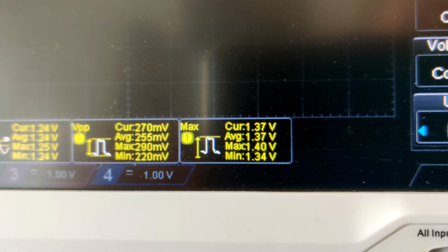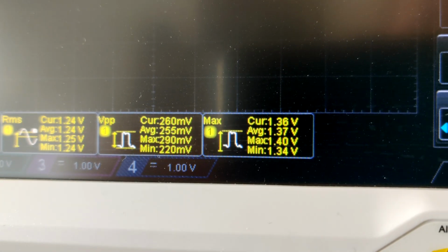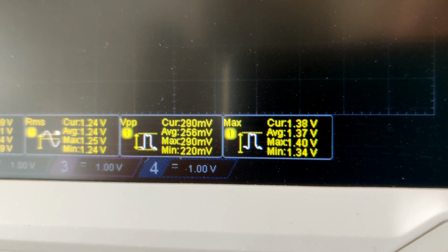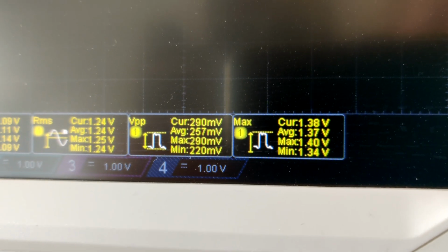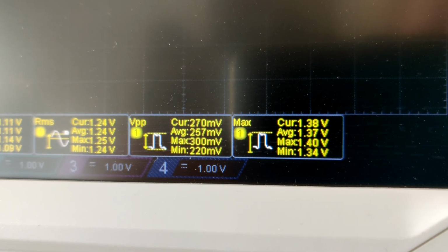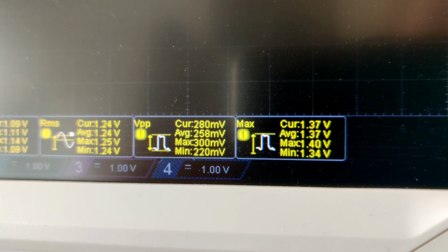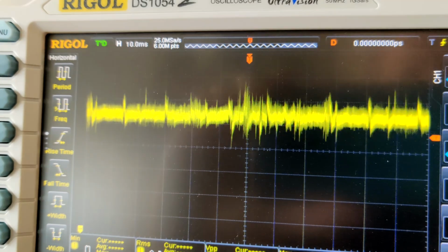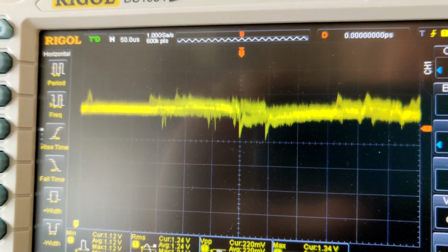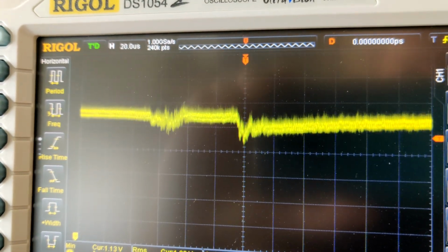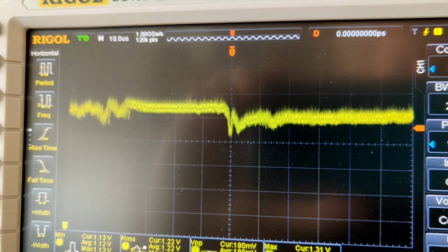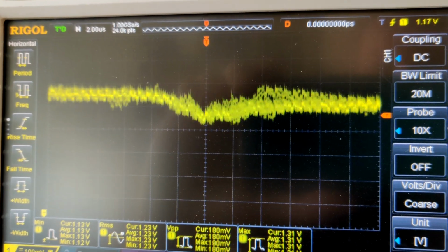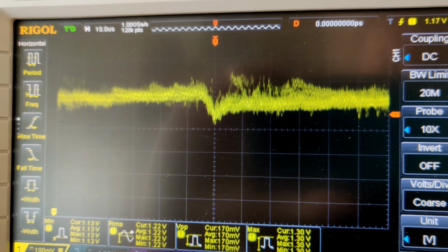They don't really do anything. Like, your maximums can go way higher than this and they won't really do any damage. A lot of people get very freaked out when they see voltages in excess of 1.3 volts. This is not a problem, because again, we're on a scale of, well, right now actually microseconds, but if I zoom back in to show one single transient happening, that's 50 microseconds, or 20, or 10 microseconds per division. Like, the actual transient event itself is very short.